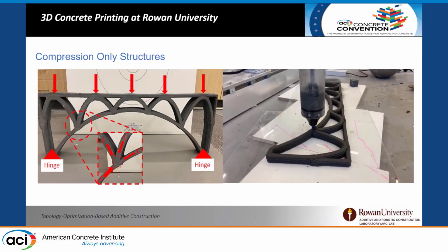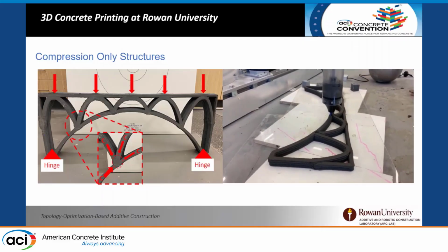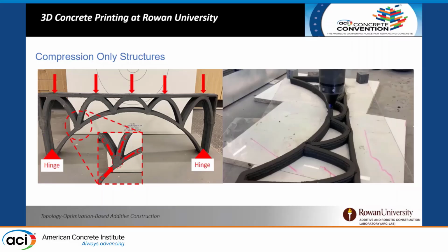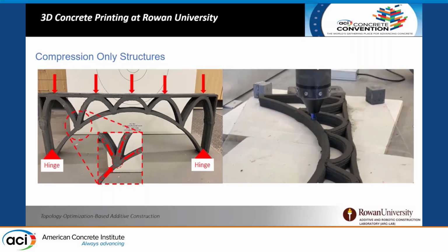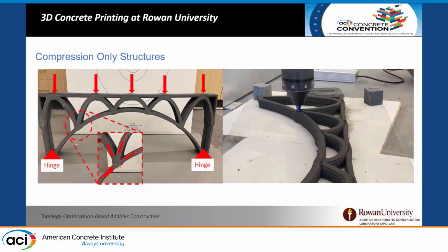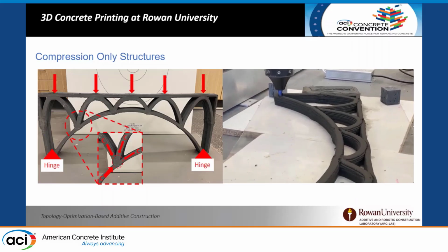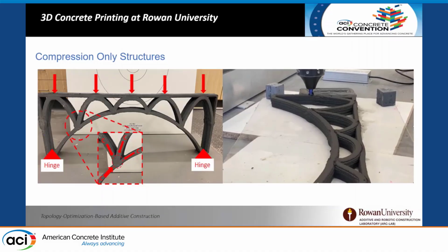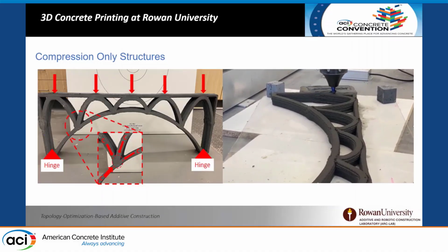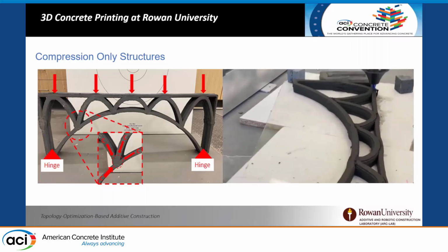So as I said before, here is a better image of what I was explaining, but with the knowledge from each simulation and each boundary condition change, it afforded me the opportunity to create a design of my own that not only had one main arch, but smaller internal arches. And so the smaller arches will carry the load until they fail, and then it will go to the main arch, increasing its capacity.